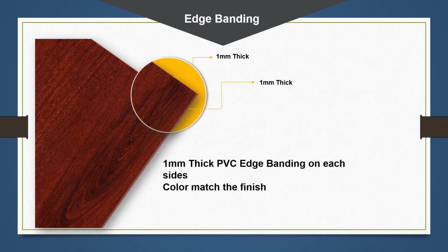Sometimes, in order to have a cost-saving option for our customers, we use an expensive and beautiful finish for the front side and use a white melamine paper as the backside finish. You don't see any edge band here, but you can still tell from the graph that only the front and back sides are covered by the finish, and nothing for the edges. We would like to cover this, for the sake of beauty and also for the sake of production convenience, so we use PVC edge bands to cover the edges here.